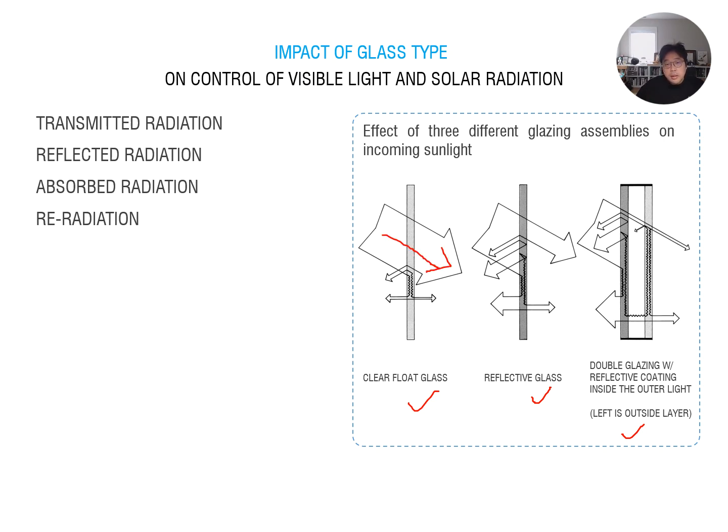However, if you have a refractive coating or a low-E coating, which is a transparent coating, it starts to reflect the sun from the outside surface, and less heat and light will pass inside. Also, with this refractive film, which is low-E film, you can reduce the heat energy from outside, and the glass thickness starts to absorb more heat energy.